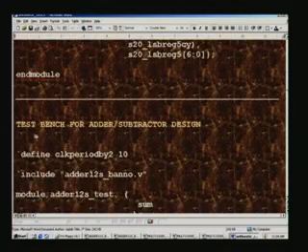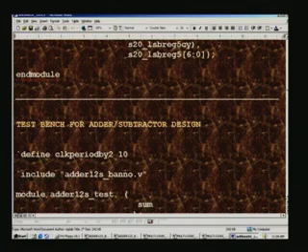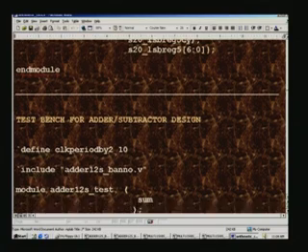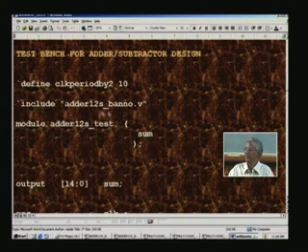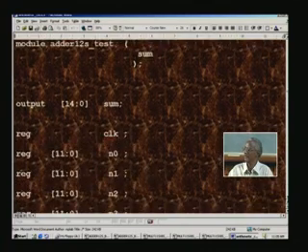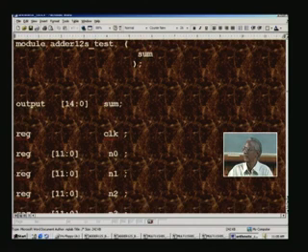We will look into the test bench for adder subtractor design. As usual, we want to run at say 100 megahertz, so we define clock period by 2, and we need to have a back annotated file for adder, and we declare the test module, which is this, and we want to return only the final sum. Note that we had used only assign statement for the sum, and therefore it is not registered, and that is why you could do it in 5 clock cycles, and if you want to register it you need one more clock cycle.